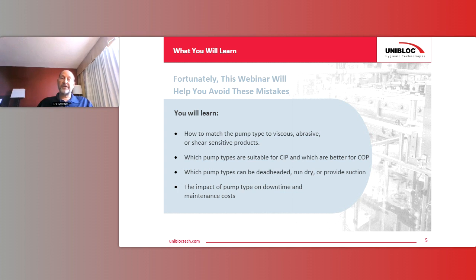The other thing to consider is how you're getting the product into the pump. Do you need suction capability of a pump to get the product into the pump, or is it going to be gravity fed and you don't have to have as much suction on the pump technology itself? And then the other important thing is the impact of the pump on downtime for maintenance costs as well as for cleaning.